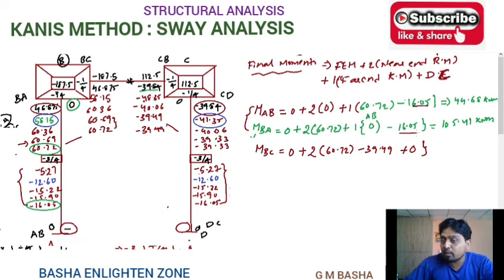These are the displacement moments. So take down displacement contribution only here for the frame's vertical members, not for the beams. So simplify this one, you will get around minus 1.541 kilonewton meter. Similarly MCB also.